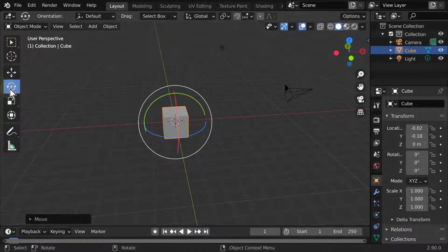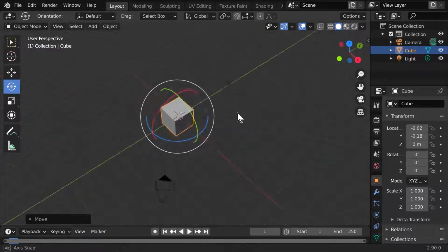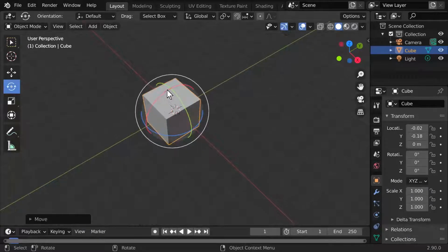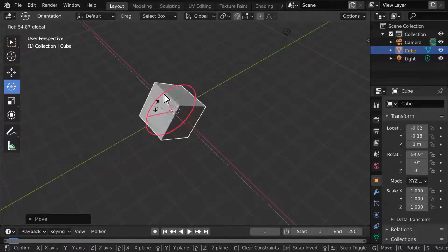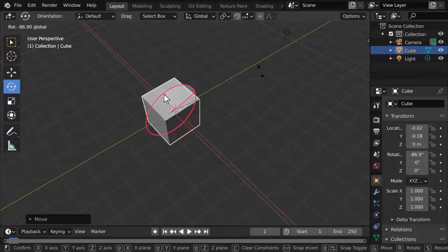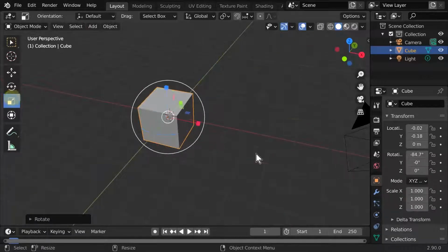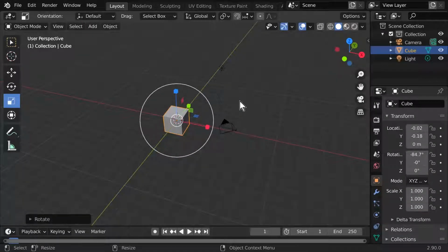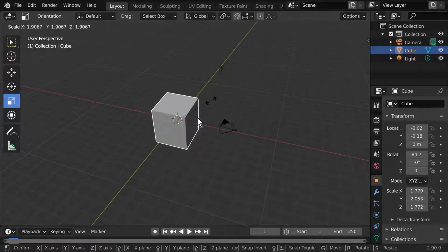Okay, rotate is this button down here. Similar sort of thing. The shortcut is E, and then you can just hold one of these dongles and rotate it like that. And finally, we have scale, which you won't want to use so much if you're working on scans because you want to preserve the scale of the original scan. But it's the similar kind of thing where you can pull these little tools to stretch and shrink your object in different dimensions.